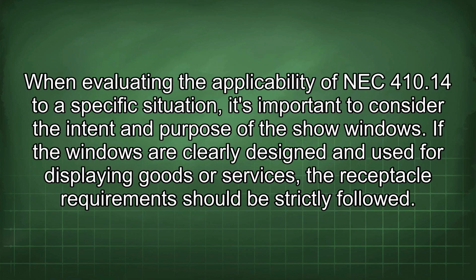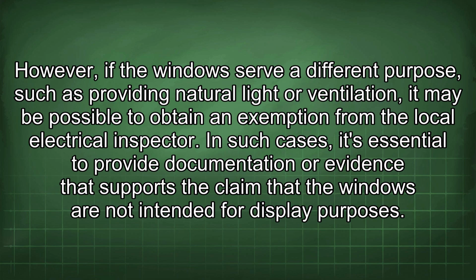When evaluating the applicability of NEC 410.14 to a specific situation, it's important to consider the intent and purpose of the show windows. If the windows are clearly designed and used for displaying goods or services, the receptacle requirement should be strictly followed. However, if the windows serve a different purpose, such as providing natural light or ventilation, it may be possible to obtain an exemption from the local electrical inspector.